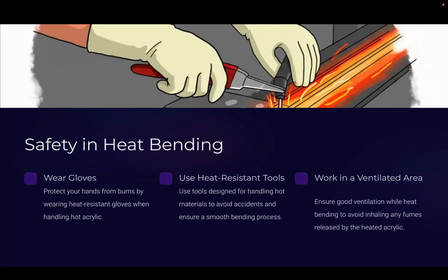And safety is important when heat bending. Please follow the following rules. Always wear gloves to avoid burns. Use heat-resistant tools to handle the material. Work in a ventilated area to avoid inhaling the fumes.